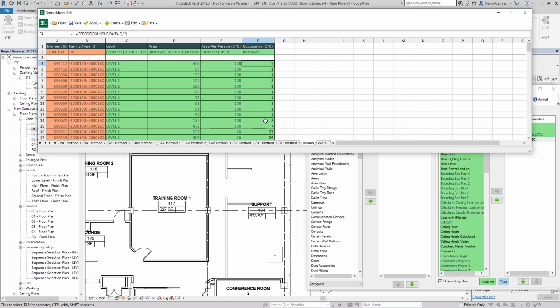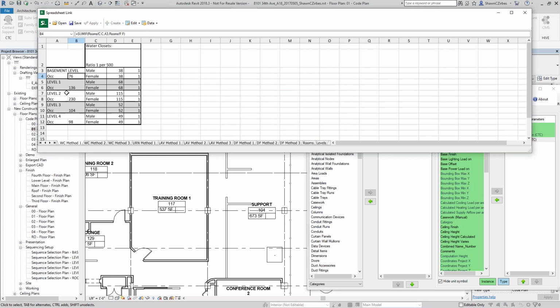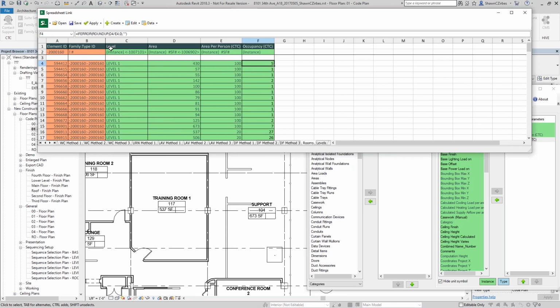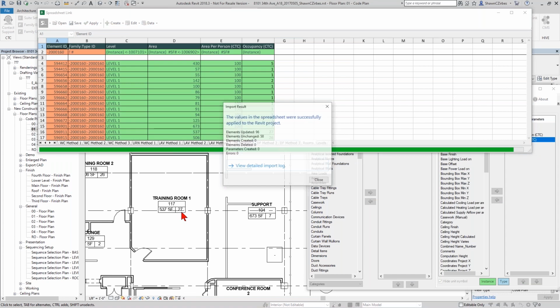When I load that setting up as an end user, it now opens the spreadsheet that I know is working. It does the maths. It goes over here. It's already looking at my data. It already does all those calcs. All I have to do if I want these occupancies pushed back into my project is to apply the active worksheet to my project, and it dumps that data right in here. So it's updated 96 of my rooms, right?